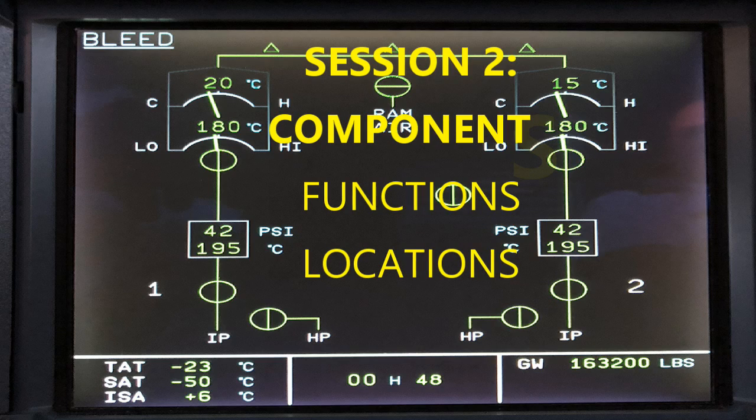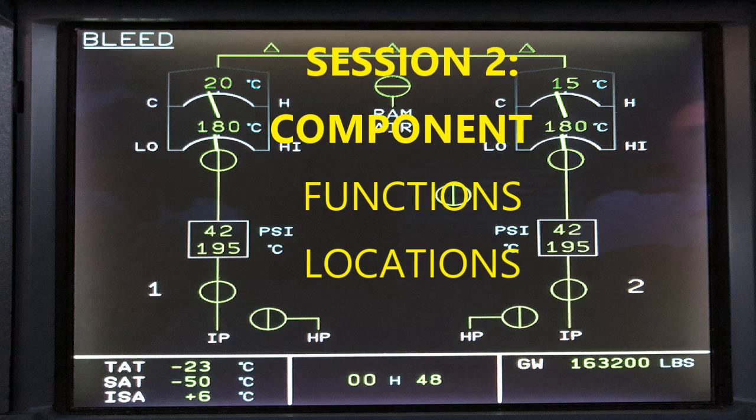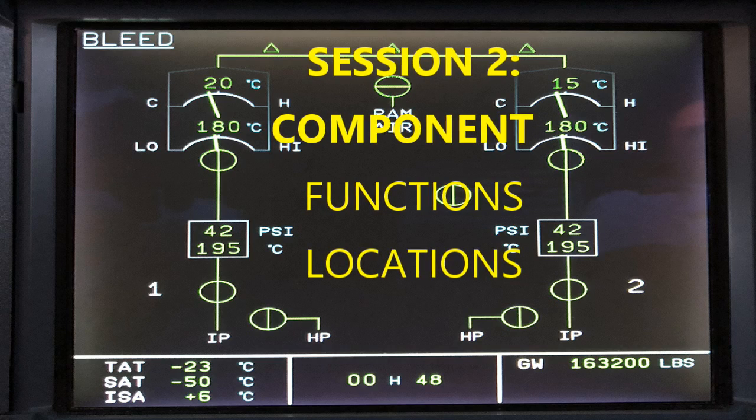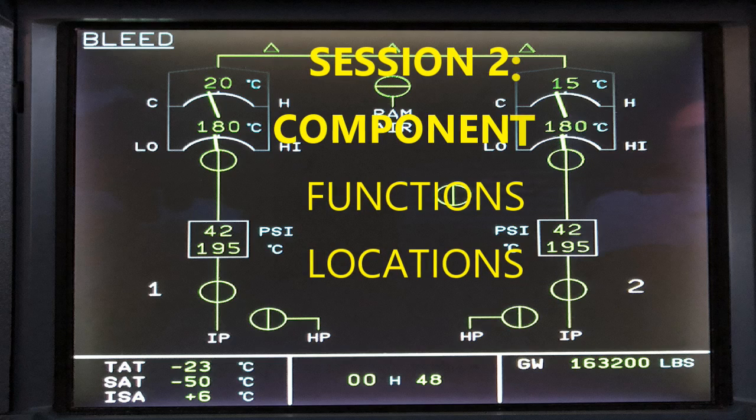And if everything's good, then it's going to tell the APU bleed valve, the load valve, to go ahead and open. So it's going to do a system check first before allowing the load valve to open. Just bottom line, that's what I'm trying to say. Which is pretty cool.